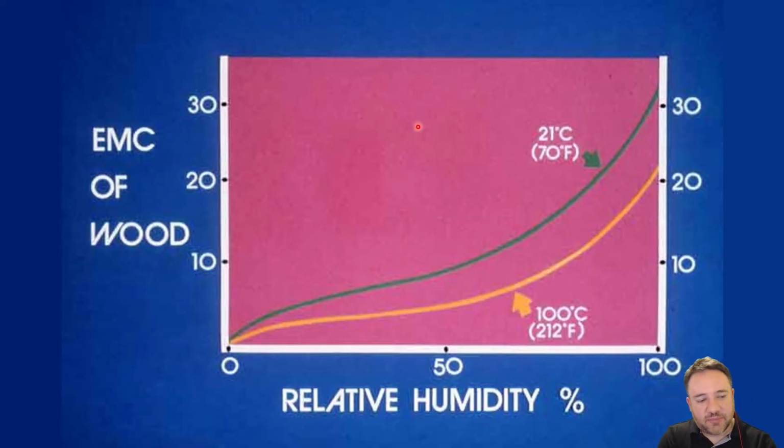Okay, as we mentioned at the beginning, wood is in a dynamic relationship with the water in its environment. So when I cut down a tree and it starts out green, it dries out. Well, why does it dry out when I cut it down? That's because in the air, there's less water than there was in the tree, right? Because the tree is constantly putting new water in, coming from the roots, coming from rain, et cetera. But if I just leave it out, the air has some water in it, but not as much as was actually in the tree due to the active processes of the tree. So that means it's going to dry out.